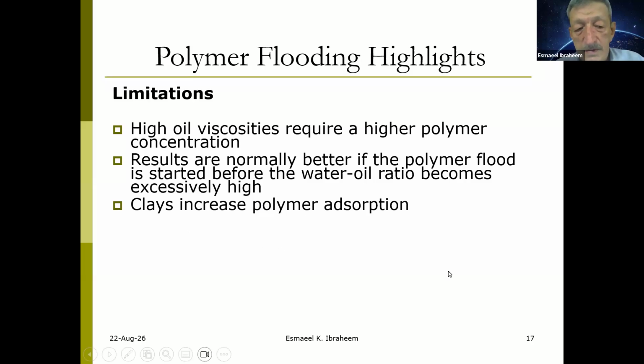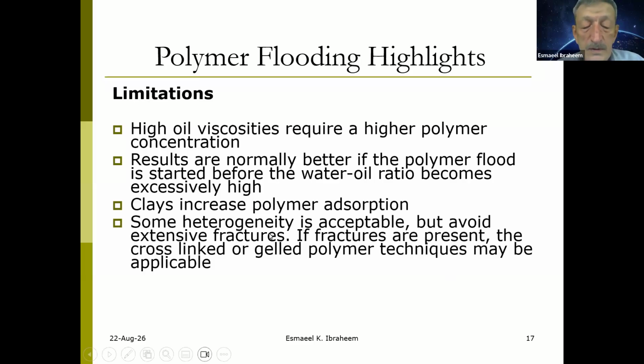Also, one of the limitations is that clays increase polymer adsorption. Clay is an eager kind of material inside the reservoir, as I call it myself. It is very eager to absorb polymers. Also, some heterogeneity is acceptable, but avoid extensive fractures.